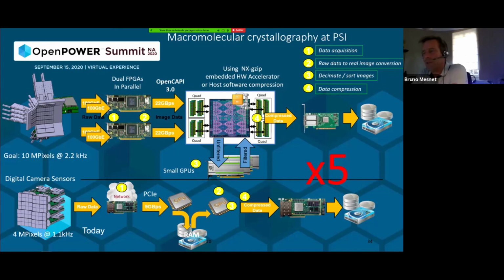So today OC-Accel is using the OpenCAPI interface. All the internal design is open source. It just, I would say, does a bridge between AXI and OpenCAPI. So as soon as you want to integrate something which can be attached to either of these interfaces, I guess you can. A2I may not be obvious, I think. Today OC-Accel is not designed for it.